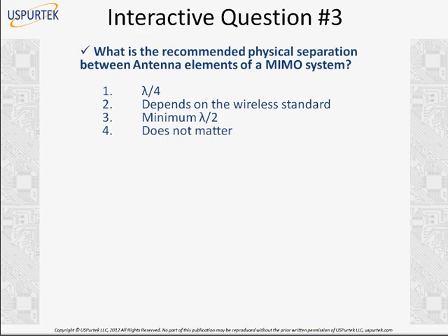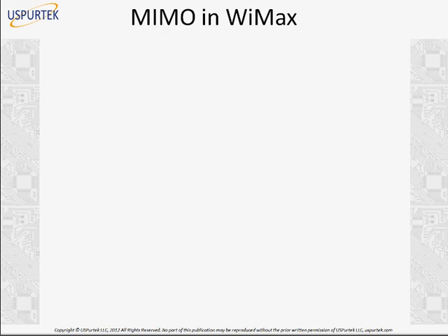You know, a transformer is a reactive device where you have a primary winding and a secondary winding, and electromagnetic induction happens between the two windings. So if the separation between any two antennas in a MIMO system is less than half wavelength, the same thing will happen, and we'll lose the benefits of this RF performance that we have been discussing.